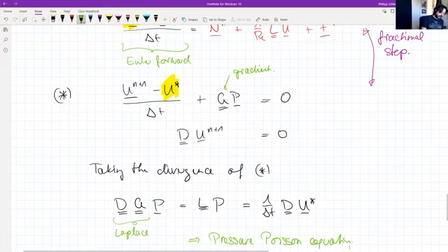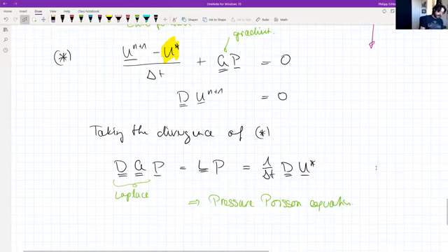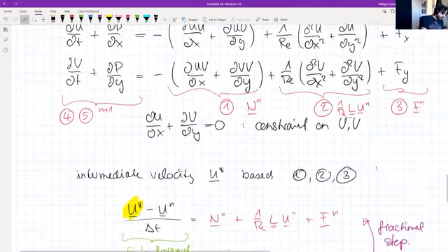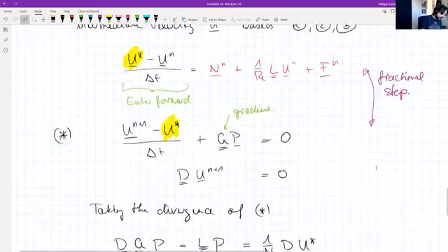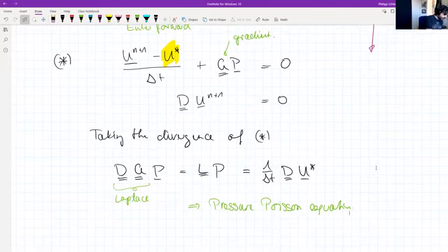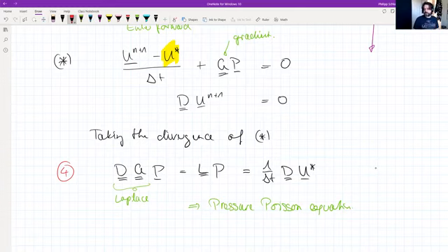The forcing term is, as you can see, just the divergence of the intermediate velocity, and that gives me then the pressure. And this is what we call the pressure Poisson equation. And calculating essentially this, or solving this problem, that is my step number 4. So I calculate a consistent pressure with my specific intermediate velocity.